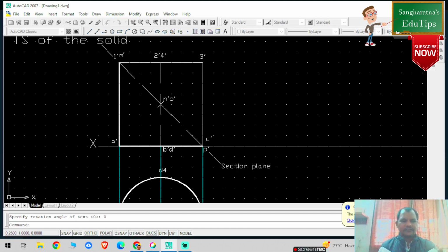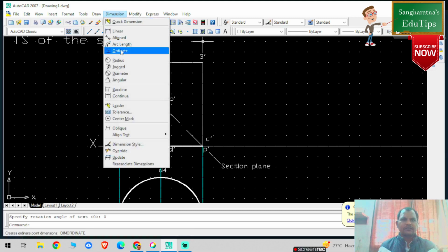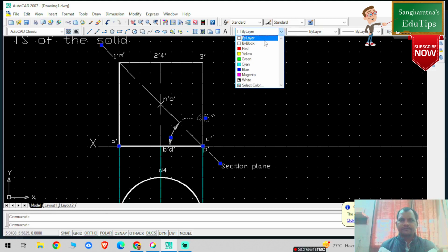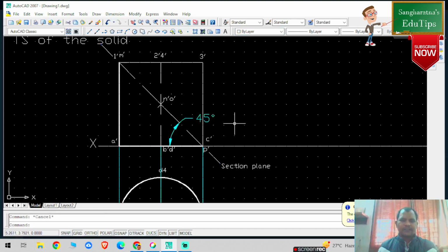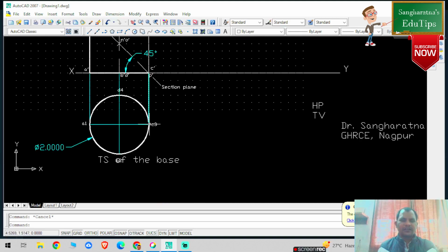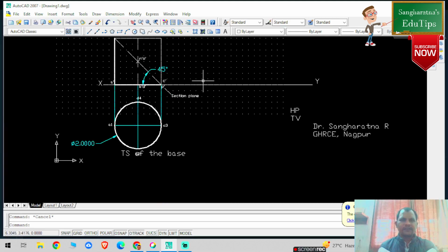Press escape. This particular section plane is cut at an angle of 45 degrees, so you can check that. Convert this into cyan color. Press escape. Right, so this particular section plane is perpendicular to the VP and inclined 45 degrees to HP.